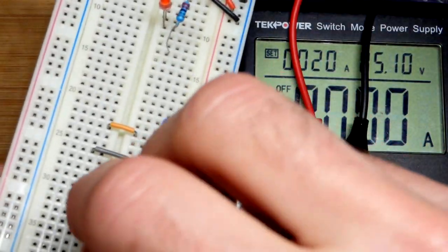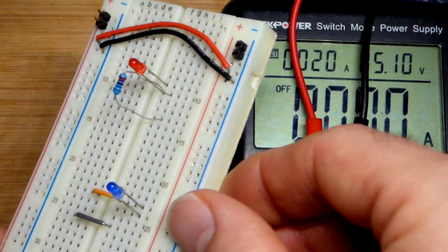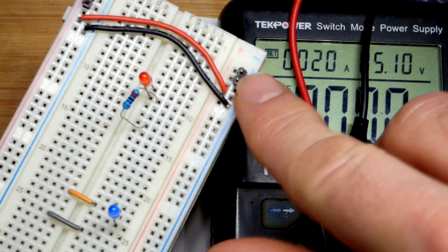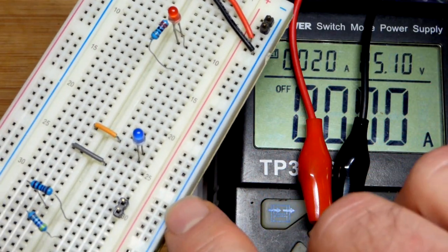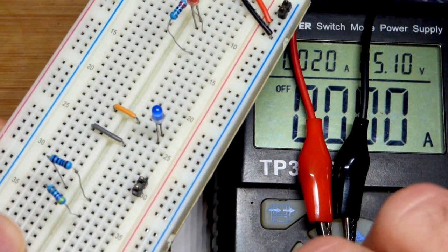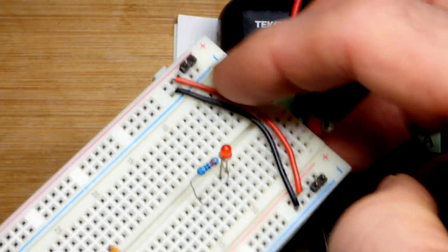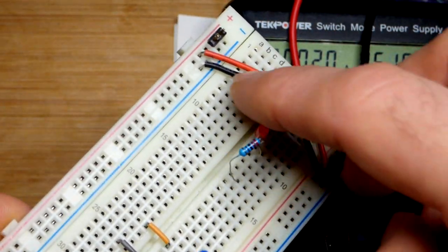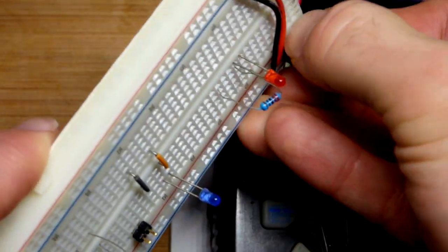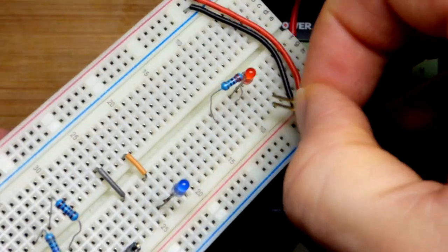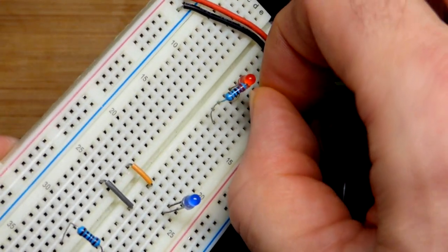You don't have to memorize the color code, but you do have to be aware of it, and it'll come quickly. So yeah, we got them in series, and this breadboard header right there, plugged into the blue row, is connected to all these holes right there, whatever I plug onto that. Same with the red one right there, and then I got jumpers to transfer them over to the other rail. That's what that's called, a power rail. But I'm just going to pluck a couple of these jumpers right there and just put them on both sides of the circuit, so we can just plug directly across the circuit.